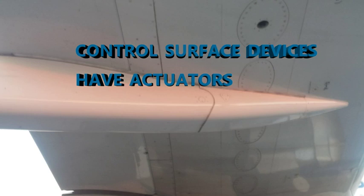You have your servo control actuators that are running your primary controls as well as your secondary. Okay, so your ailerons, elevators, and your rudder. For your outboard ailerons, there are 2 servo controls running each of those. And then for your inboard ailerons, you have 1 servo control actuator and 1 electrohydrostatic actuator.